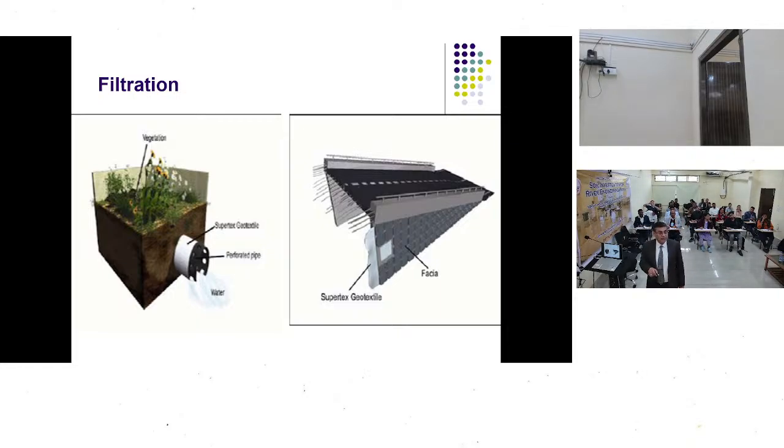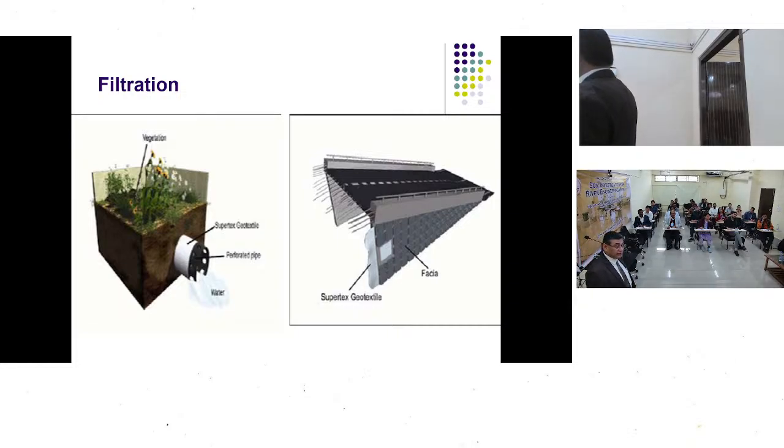The second application is again in road embankments. These are the fascia panels, which are connected through reinforcing sheets. Sometimes we put geogrid, sometimes steel strips. Along the vertical face of this fascia, I can install a piece of non-woven geotextile which will act as a filtration layer.